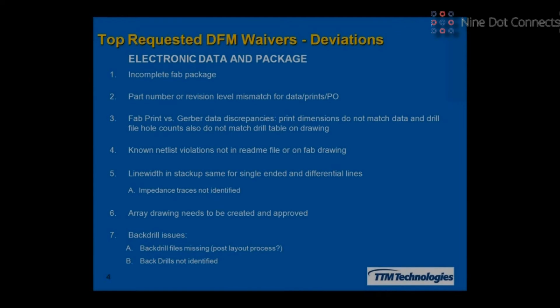So this is kind of an interesting subject, because depending on really where your camp is, I know that the military folks like to leave them in, and digital commercial guys like to pull them out. And on the fabrication side, we like to pull them out. And the reason being is, it's harder to drill through copper than it is through fiberglass. And so if you only have the pads that are necessary in there, it has a longer tool